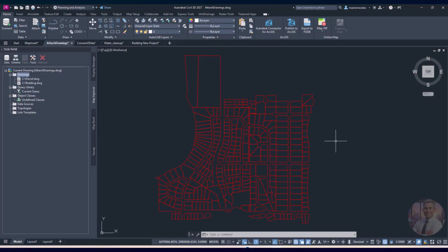By the way, a little bonus tip for you, in case maybe your wheels are turning right now and you're thinking, well, why don't I just open both drawings and copy and paste them in? When it comes to working in Civil 3D, almost never use copy and paste. Okay? Copy and paste is a Windows function. It uses the Windows clipboard. It understands simple things like text. I want to take this sentence and copy it and paste it over there. It does not understand intelligent objects.